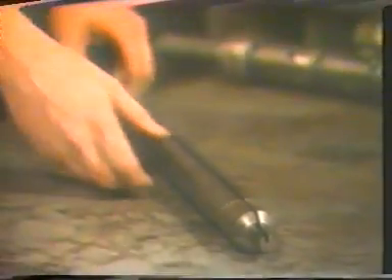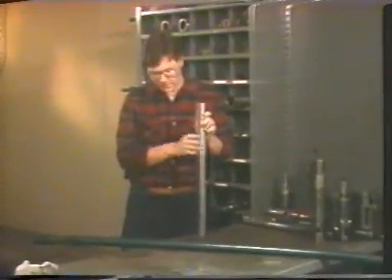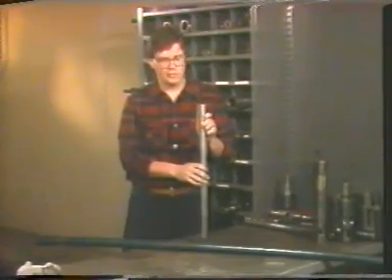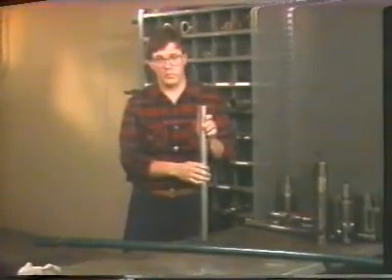The Kinley snapper is another tool designed to cut the wire line at the wire line socket. The assembly is allowed to fall into the well pinned to the wire line, and when the snapper strikes the wire line socket, the crimper and knife force the slipper to move sideways in the tool, cutting the wire line between the slipper and the knife. This action also crimps the wire line between the crimper and the slipper, which allows the snapper to be retrieved with the wire line. Like the cutter bar, the snapper must have a solid base upon which to work to cut the wire line. If there's any doubt that it will be able to reach the wire line socket, a go-devil may be dropped ahead of it in order to give it that solid base.